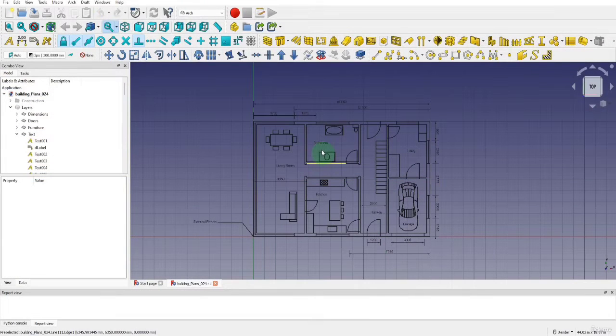There are different methods to display your drawing in FreeCAD. For this example, we will use a section plane. A section plane can be used to cut through a model and create elevations and sections. In our case, any object selected when creating the section plane will be visible within the layout.